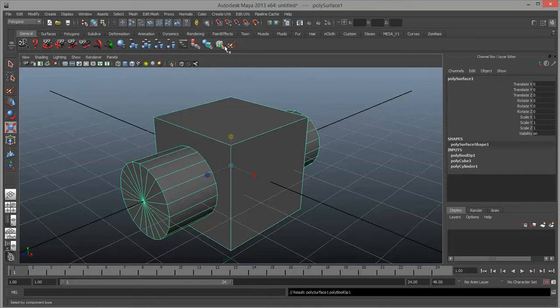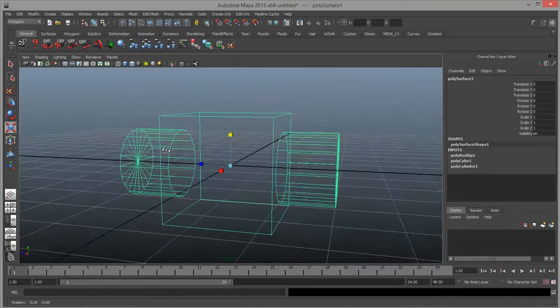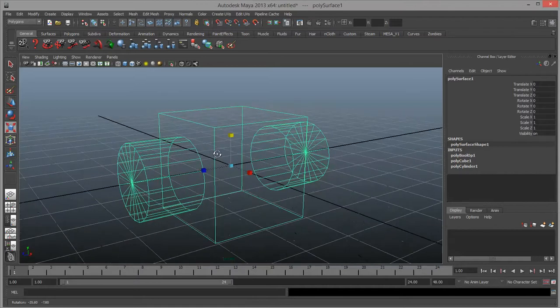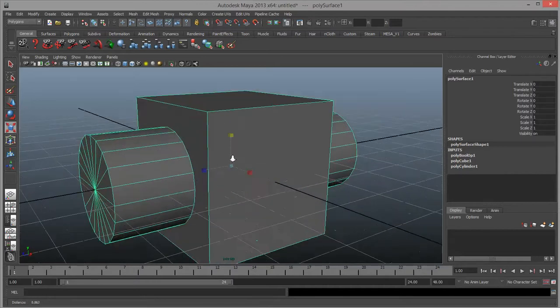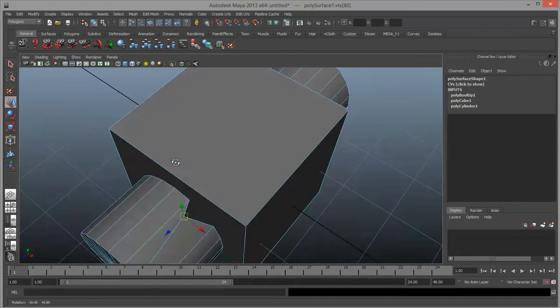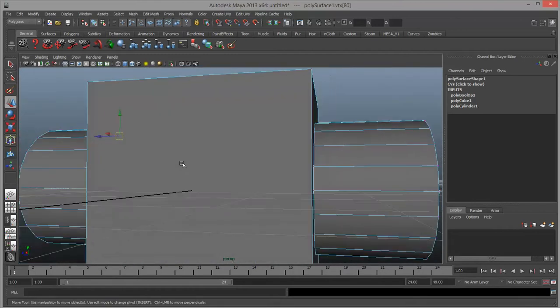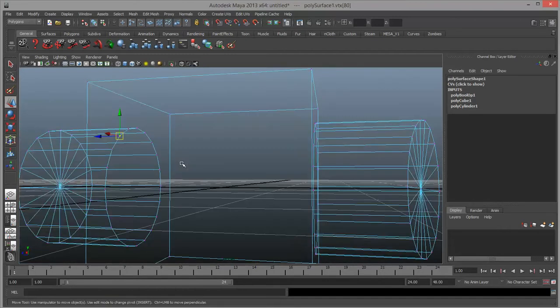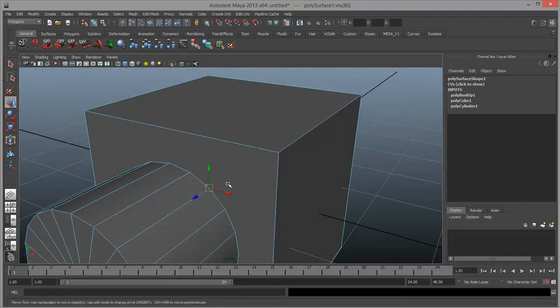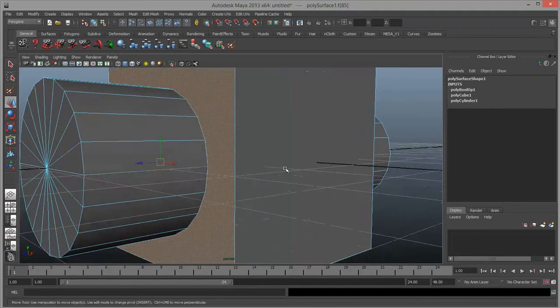For union, the two objects are going to be combined, but whereas there used to be cylindrical information going through the center, now there's nothing. Now it's completely sewn together with the cube, and in fact, if I move these vertexes, you can see that it's going to affect this face. Well, you can kind of see that. You may already be seeing one of the problems is that although this combines the two pieces of geometry, it does not create edge loops, and it does not draw that information into the surface. It creates horrible, gigantic n-gons.